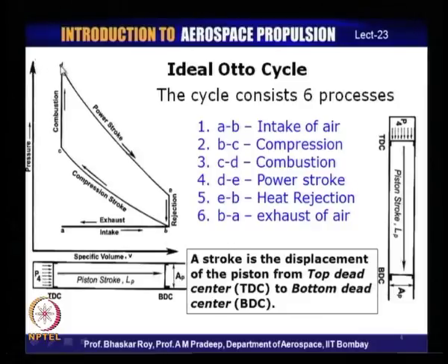So, it goes to a higher pressure at D. Now, at this high pressure and temperature, the cycle now does the process of expansion. So, from D the process is expanded, which in engine terms is called a power stroke, and it expands from D all the way down to E, and that is the end of the process of expansion, which is also called the power stroke.